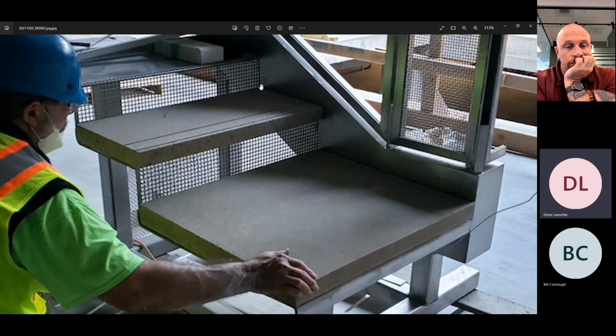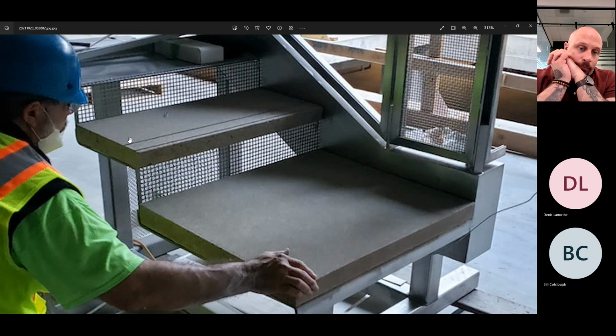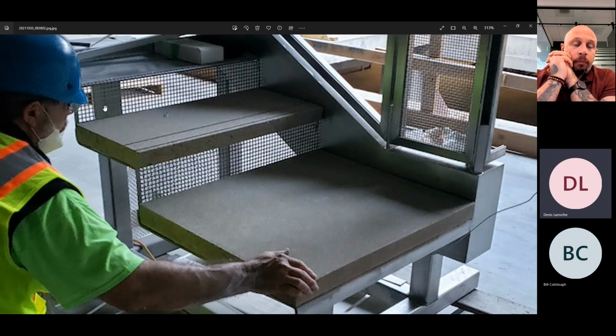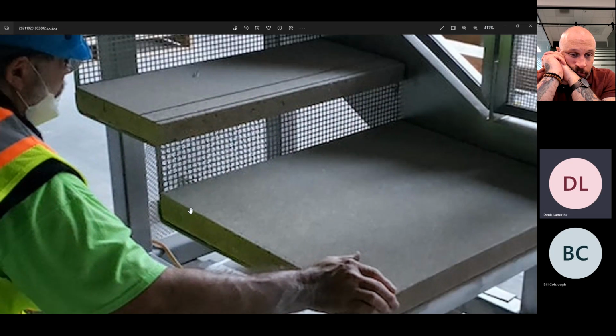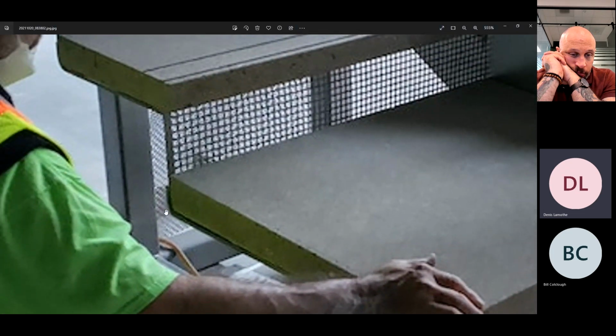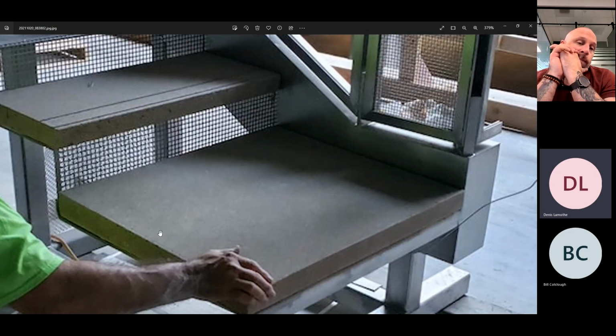So it's generally recommended if we do terrazzo treads that they have a 1/4 inch gap between the stringer and the terrazzo. And this would apply to any other surface that it would be in contact with. So in this case, where we have our precast up against the riser, you might not see it too well in these pictures because they're made with like a potato that acts as a camera. But there's a bit of a gap there between the riser panel and the precast. So wherever precast would touch something else, we try and leave an eighth to a quarter of an inch gap there for those fabrication tolerances.